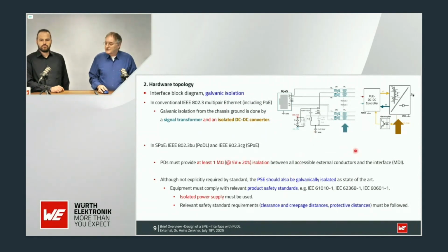You may know from this Power over Ethernet standard that we have here a flyback converter or forward converter, which isolates then at the PD side the secondary side of this device for the power supply. But here you remember we have coupled all the energy only by inductors, meaning there is no galvanic isolation. So this must be additionally taken care of if you make this design.